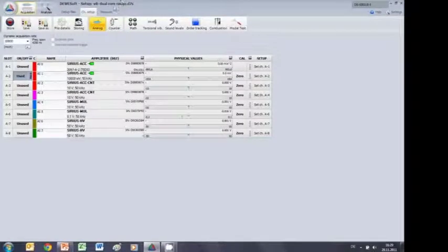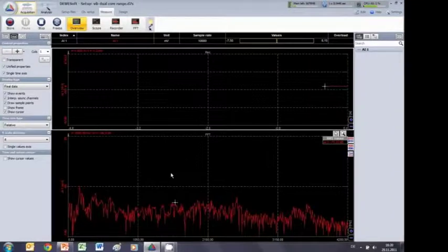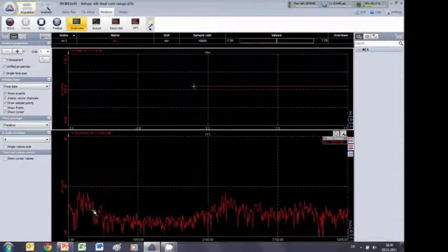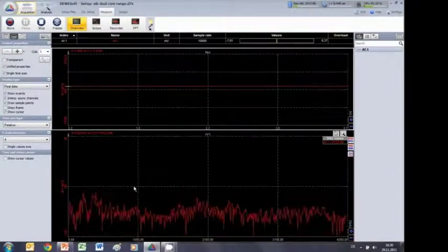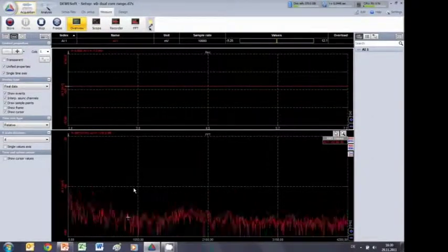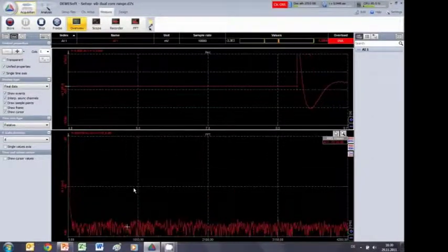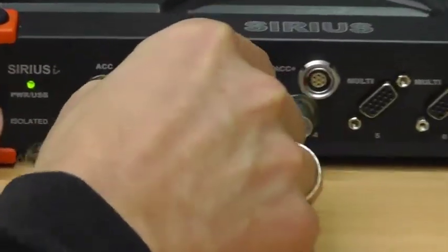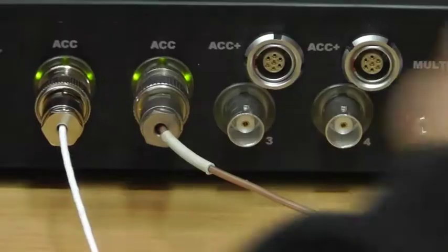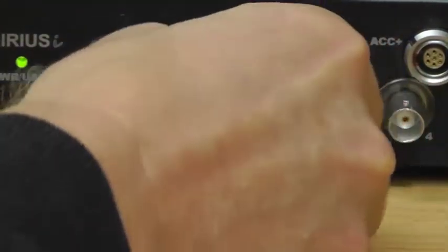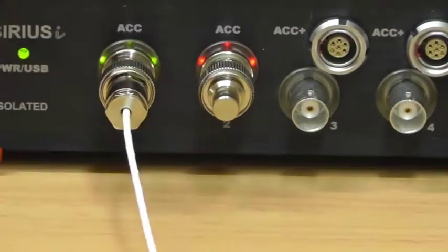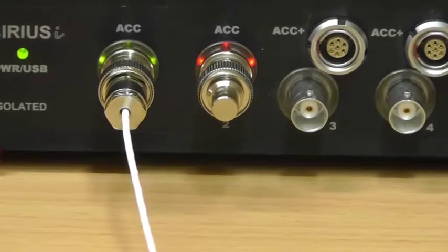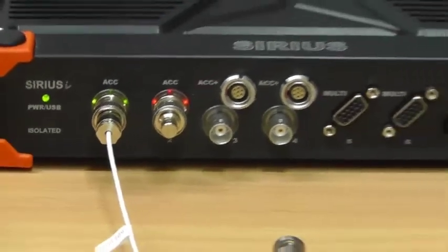Going back to acquisition, what does it mean, huge dynamic range? The dynamic range is measured in dB, in decibel. To show the full dynamic range of the system, as you can see now, the lamp goes from green to off. So back on, you see green, that means the current to the sensor is okay, that means the sensor is okay. If I now short circuit the input, you can see the signal goes to red, so it's now short circuit.